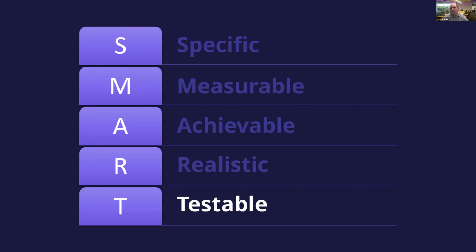And testable. This is covered somewhat in the steps above, but it's very important that you ask yourself, how can I test every requirement listed in the FDS or URS? In particular, consider cases where the machine is to work downstream of existing equipment, such as a high-speed packing line, where it is not possible to feed enough parts at speed to the machine during the internal and FAT testing.